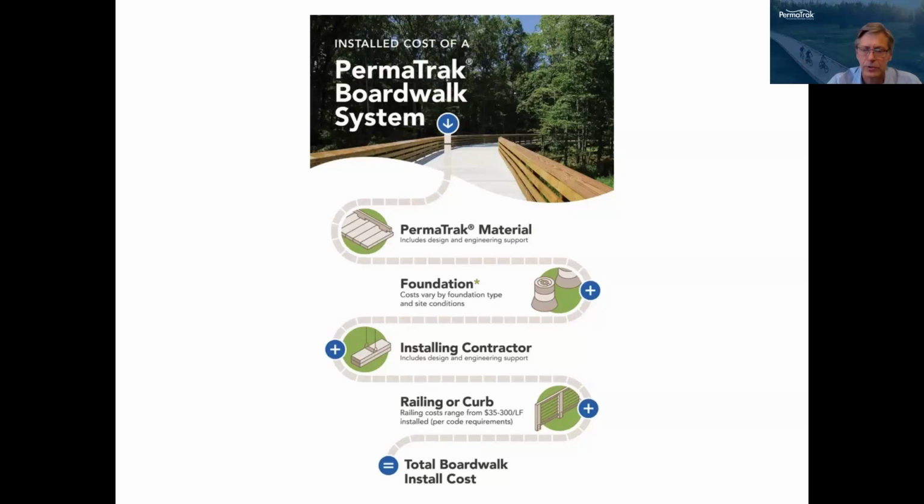So that's why it's so critical that you get a geotechnical report early, so that you can make a good decision on a foundation type. And then if it's a more expensive foundation type, you may want to use a custom beam design and go to 30 foot, even though your precast cost is now higher. At the end of the day, you actually saved money because you reduced that expensive foundation. And those could be $10,000, $15,000 per pile. So if you cut half of them out, even though you spent more money on your precast, at the end of the day, you delivered a lower total cost for the project.